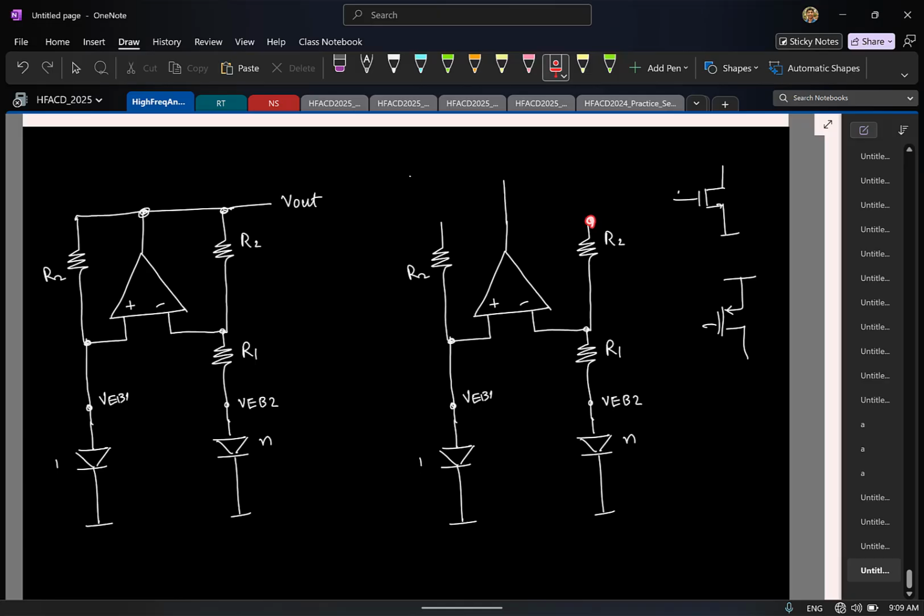If I were to connect the load here, I will connect to the drain, source or gate of the transistor. Drain. From drain I have to connect it to ground. Which is easier, you think? For PMOS I can directly connect the load here and get it done, right? Otherwise for NMOS you'll put something to the supply and then you have to put a bypass cap and put the load something, right? So PMOS is slightly easier, so that's why we use PMOS. It's a consideration, does it make sense? It's not like you can't use NMOS, but with PMOS it is easier because you directly connect it to ground and it's done.